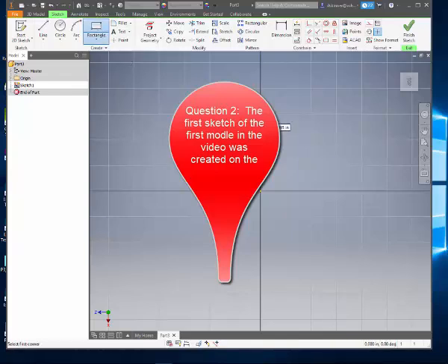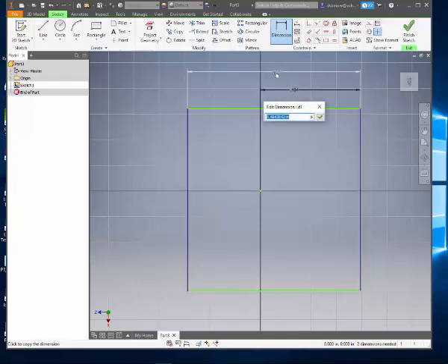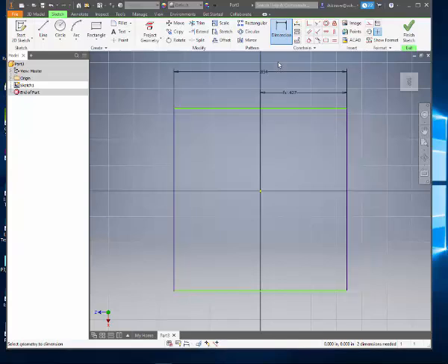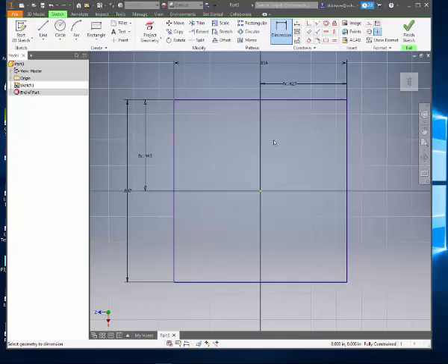Then I'm going to create a rectangle, and then I'm going to dimension it. I don't really care what that dimension is yet, because I like to tie in the center point in reference to that, so that when I change the dimension, then the center goes with it and it doesn't try to offset in some weird way. So again, this one, the center, this dimension divided by 2, and now I can change, let me right click to get out of the dimension command and choose this one.